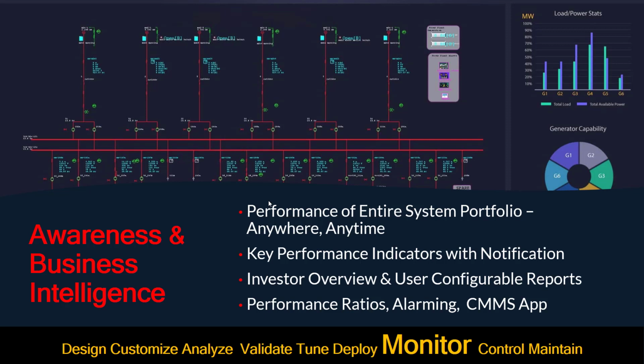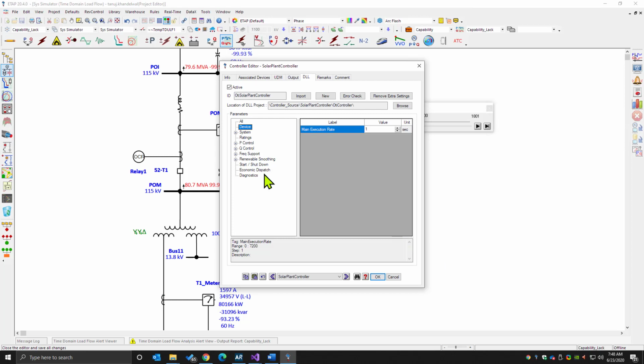And these can also be supplemented with schematics of the one-line diagram, so you can visualize and understand the status of various components in the electrical system. So therefore, when we look at the parameterization for the power plant controller and we see all of these values such as P control, Q control, renewable smoothing, and so on, when we deploy this logic, it essentially is available inside our web HMI as well as SCADA system, so that certain individuals who have authorization and access can also change the parameterization when the system is online.